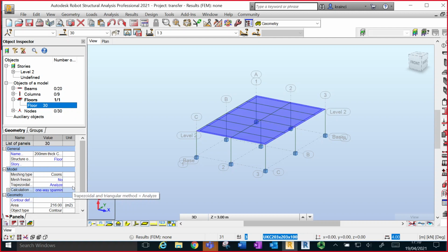So that is one modification. One more thing that we need to think about is our beams. When you do your design, you are assuming your beams, secondary beams, primary beams, normally to be simply supported. In some cases, you have continuous, but that requires moment connections, and most often steel structures will just have simple connections. So let's change our beams so that they have simple connections or pins.